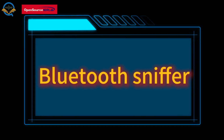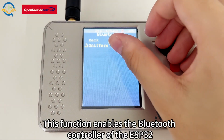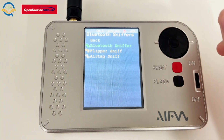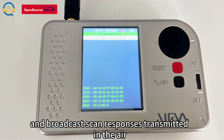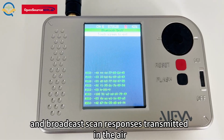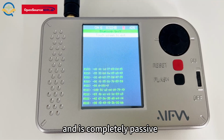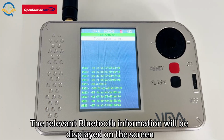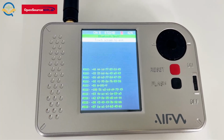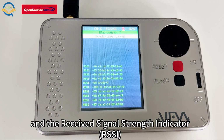Bluetooth sniffer. This function enables the Bluetooth controller of the ESP32 to enter the listening mode, capturing the Bluetooth broadcast packets and broadcast scan responses transmitted in the air. It does not connect to any device and is completely passive, thus not being detected. The relevant Bluetooth information will be displayed on the screen, including the Bluetooth MAC address of the transmitting device and the received signal strength indicator RSSI.